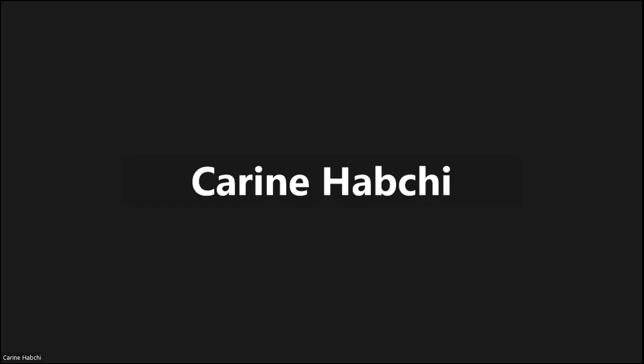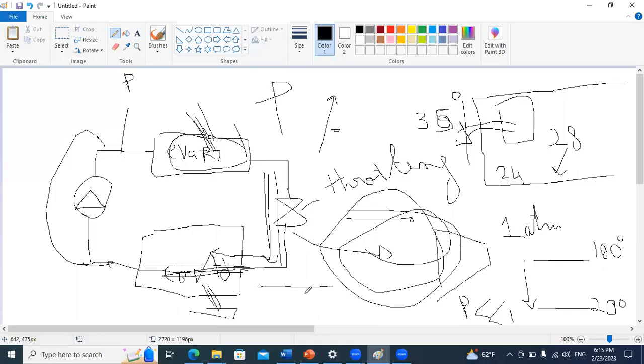Okay, so we were discussing the refrigeration cycle. We said the idea is to operate the fluid in a cycle in order to force it to take heat from the position I want and to reject heat in the position I want. So whenever I want to produce a cooling effect in my room, my room should be on the side of the evaporator, because at the evaporator side, the fluid circulating in my system will take heat, while at the condenser side, it will reject heat.